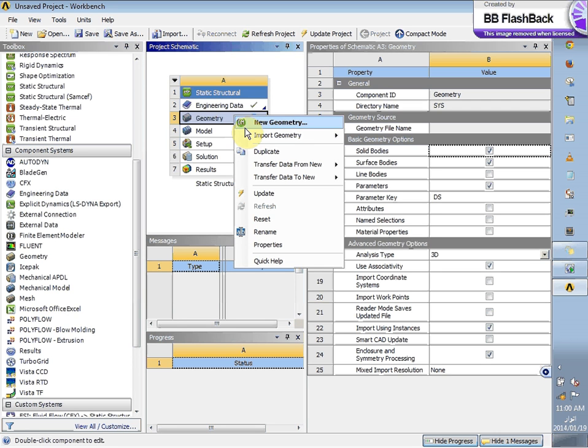It comes with Ansys. To use Design Modeler, you can create a new geometry or import a geometry, for example this SAT model we used that was developed in AutoCAD. We saved it as a SAT model and imported it in Ansys here. Or you can use any other model that you have created in any other software, CATIA or ProE or Creo, any other software. You can import it from there too.